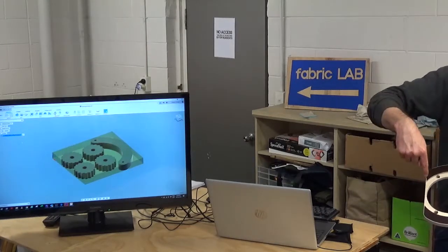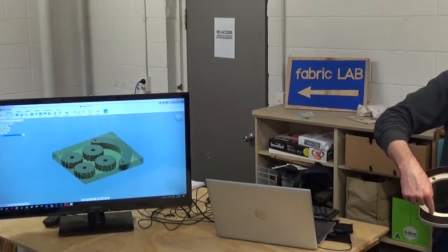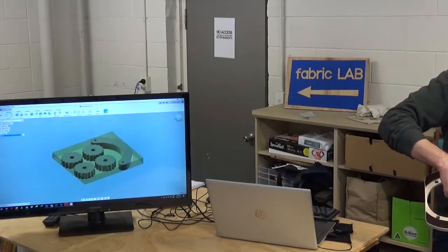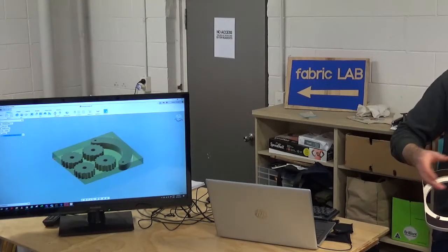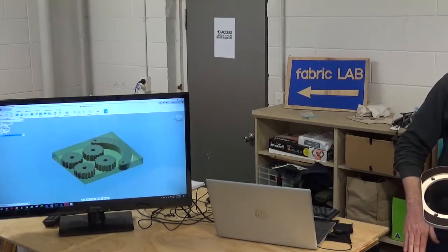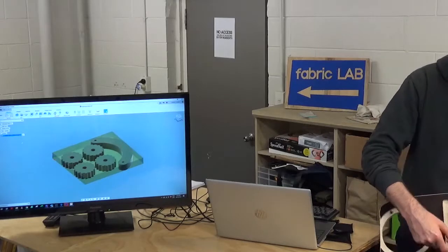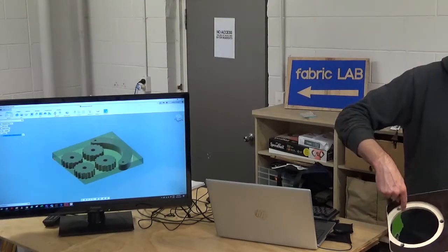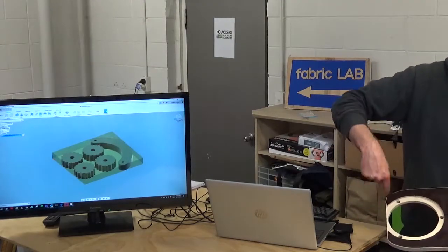So these two pieces were cut out from inside. That's how you try and make use of the material, right? So an example of this: the first thing we did is drill these holes. Then we went and pocketed in here. That's a pocket, which means removing material but not going all the way through. The last thing we did was profile. So we profiled in here and then profiled around the outside.